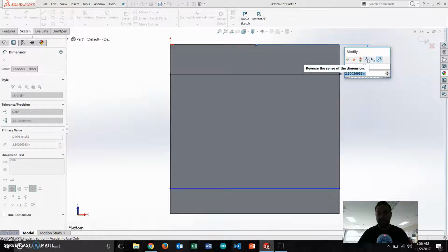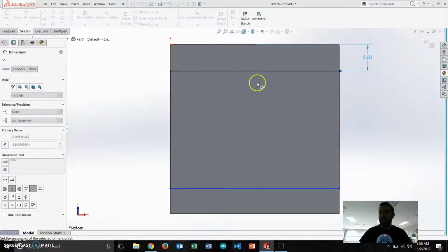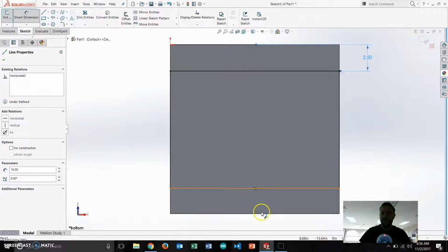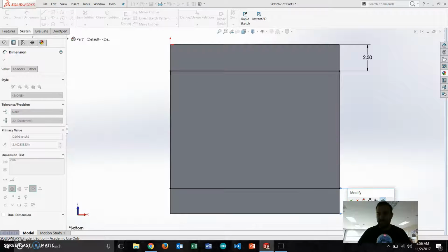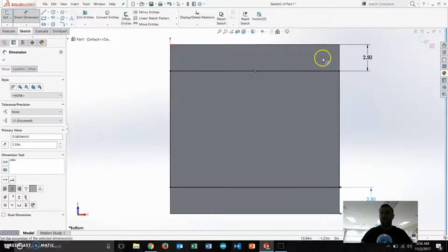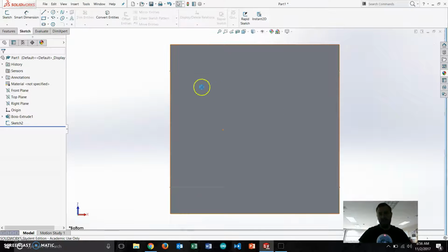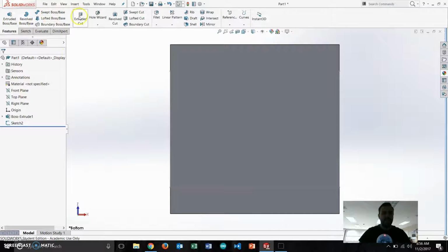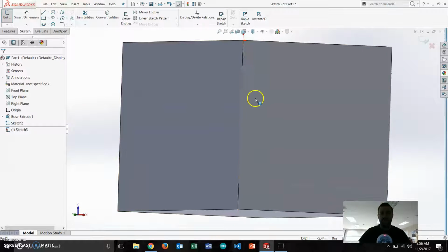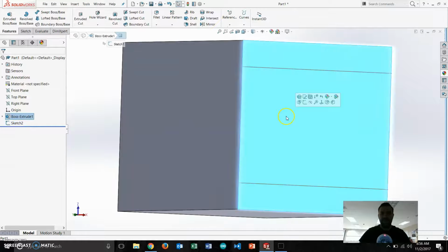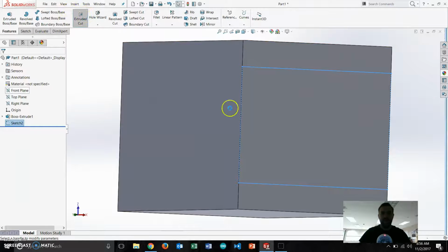Let's say I want the legs to be 2.5 inches wide, so I'll do 2.5 there, and 2.5 here, 2.5, and now I've got 2.5 inch long rails on either side, and that seems like it'd be a cool stool. I'll do that, go back to my features, and now I want to do an extruded cut of this. SolidWorks has a little bit different procedure where you can choose an extruded cut. We're good here. Choose that sketch. And now I want to do an extruded cut.